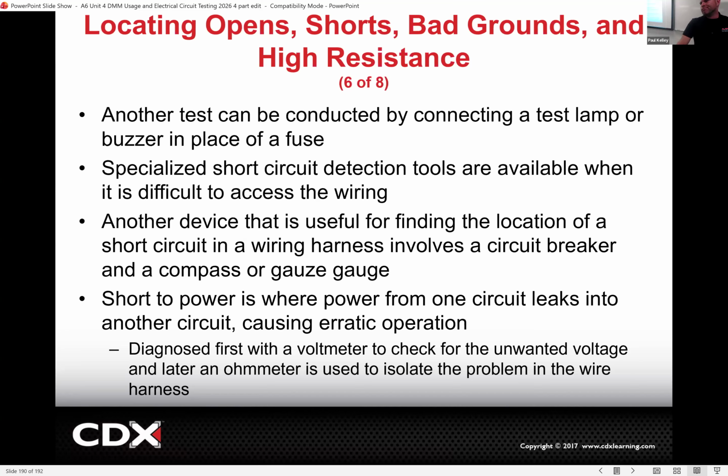I know a lot of people don't really use this because it may be used on trailers or something where it's more accessible. But if you're trying to use some of these specialized equipment, it kind of covers for you not really knowing what you're doing that well. Also, in a car, a lot of the wiring is hard to access. It's behind panels. These specialized short testers and open testers, you need to be almost right on the wire. So you'd have to pull a lot of interior panels off and then run it across the wire.